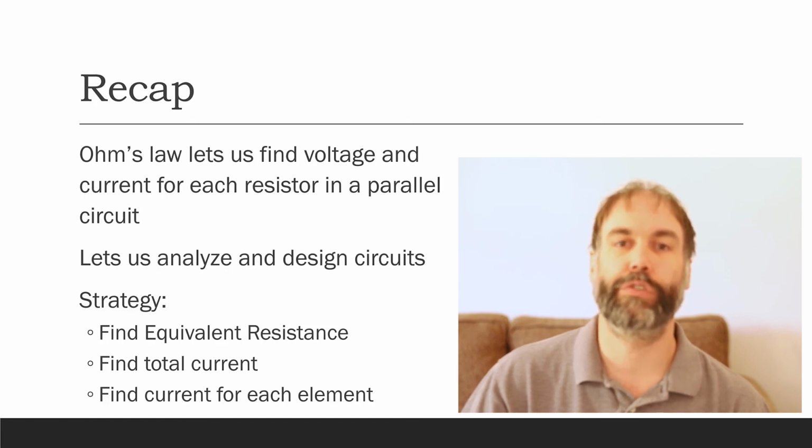And remember, the voltage for every resistor in a parallel circuit is constant. The voltage is always the same as the power supply voltage. So that's a little bit of information about using Ohm's law in a parallel circuit.